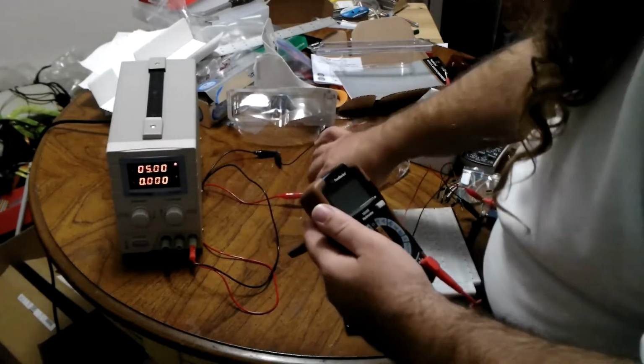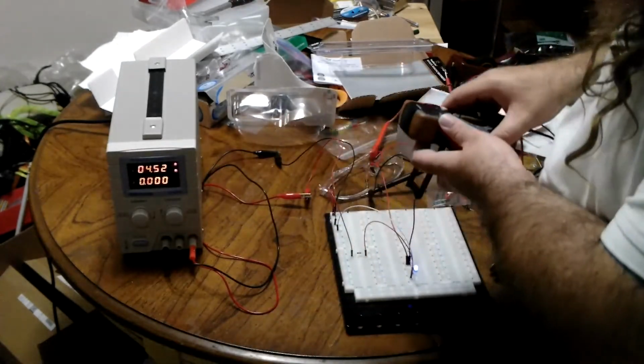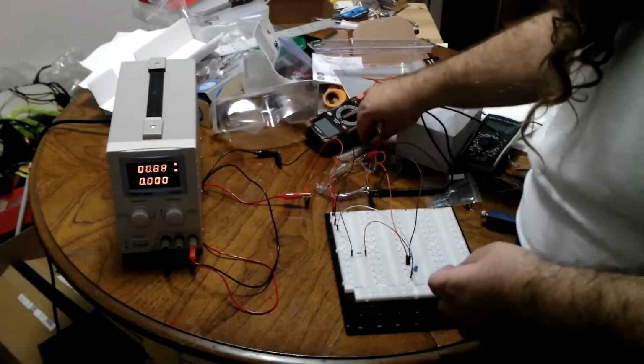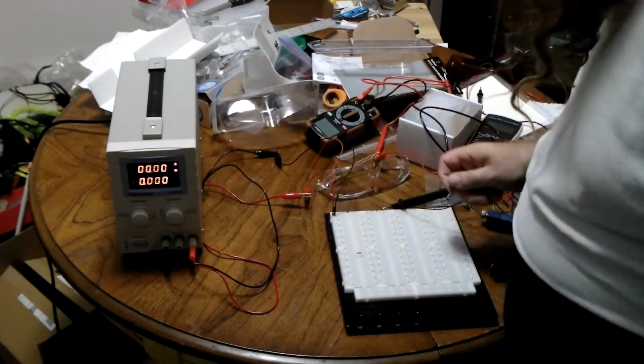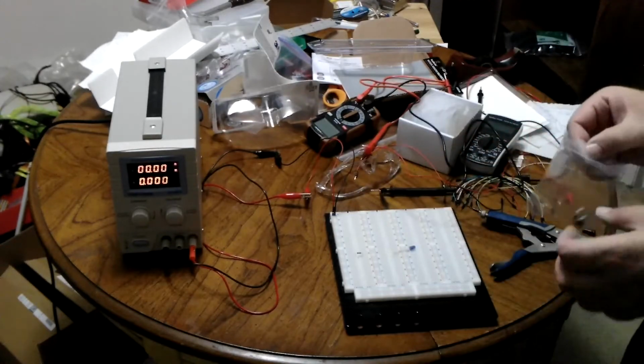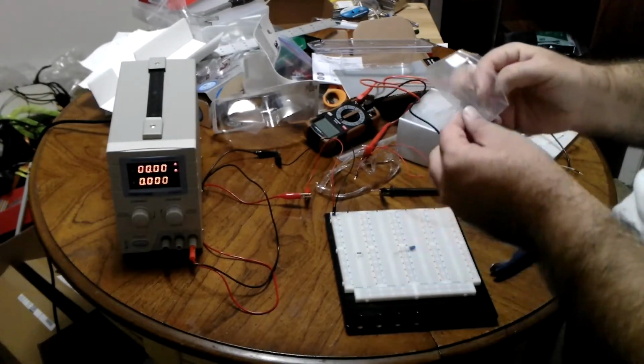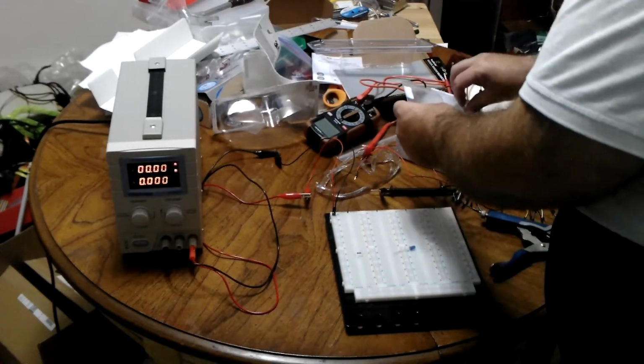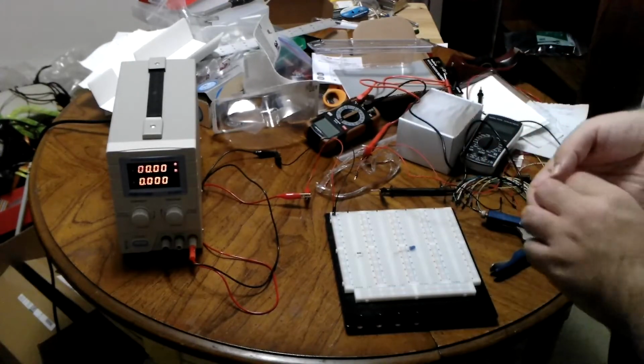Let's demonstrate Joule's law, the power. Remember to turn your power down when you disassemble your circuit so you don't touch something you don't want to touch. So now, I'm going to get a resistor that is 1 ohm. Why am I doing this? To make the math easier. These resistors are rated for 1/4 of a watt.